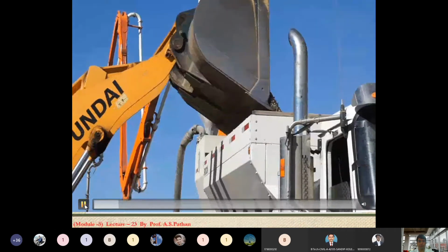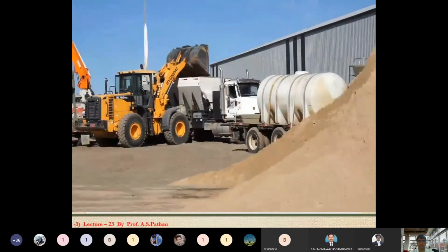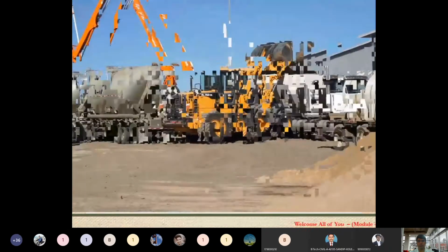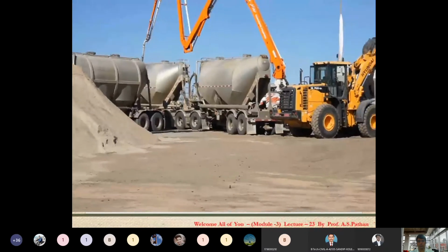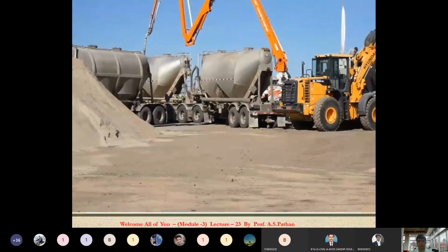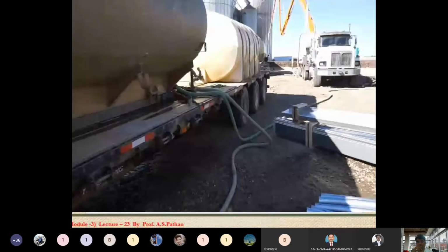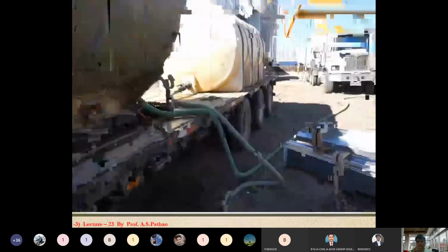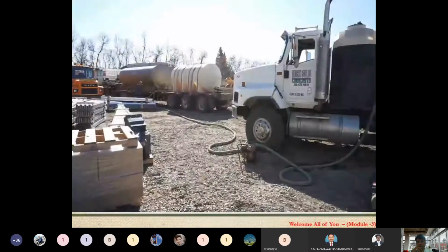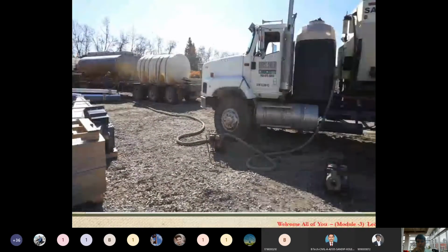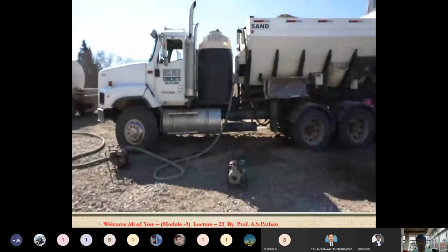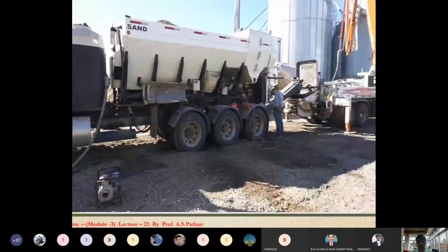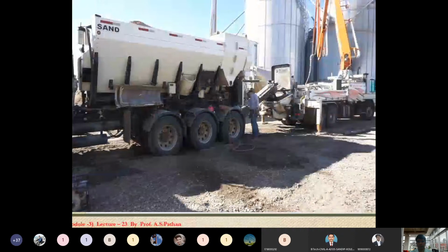As we're pouring, we have a water trailer there too that I'll show you. And there are cement bulkers that keep filling the truck up as well to keep the powder full as we pour. So here we got our water trailer hooked up through that hose, and we just keep that water tank full as we're pouring continuously. So we're pouring into the pump there.